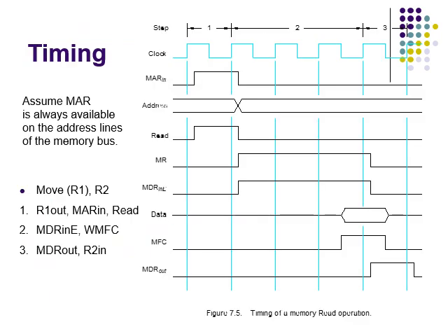let us assume that the output of the memory address register is enabled all the time. Thus, the content of the memory address register is always available on the address lines of the memory bus. This is the case when the processor is the bus master.